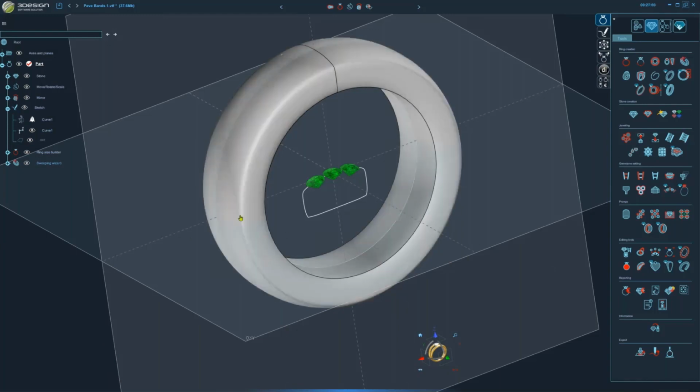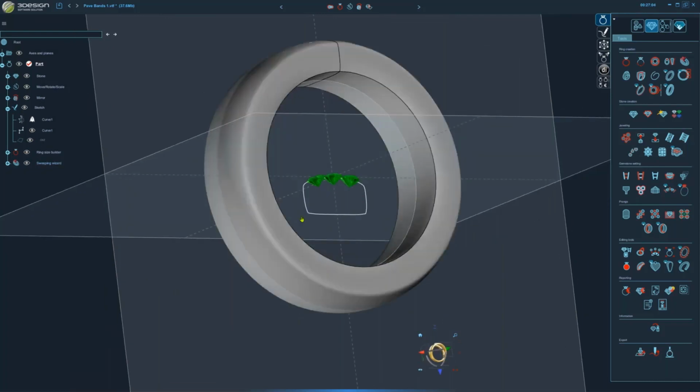Once I add my pieces and cut this in half, we'll have a nice, clean, simple surface to work from on the bottom. So I just wanted to point that out, talk about how you can control the topology of your pieces by taking care of how you draw the pieces, the sections, and using some of those options to choose how it's divided up, the single surface option, and then choose where the starting point is. You can do all this manually too.